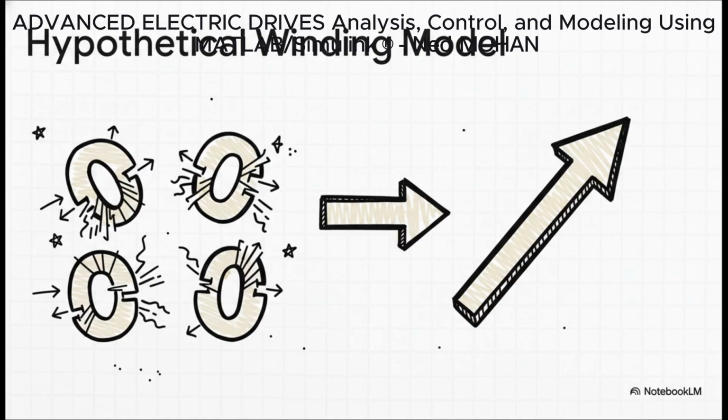It makes the same magnetic field, it has a current related to the peak, and it points in a specific direction. So why do we care? Because now, when we want to calculate something like torque, we only have to deal with one winding. For anyone designing a drive controller, this is an absolute game changer. Your algorithm doesn't have to juggle 3 variables anymore. It just has to control one vector. That's what makes modern, high-performance motor control even possible.